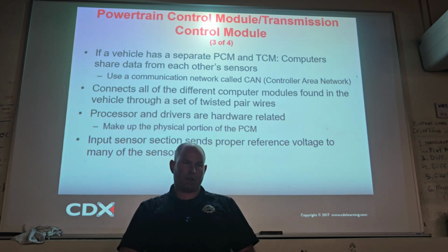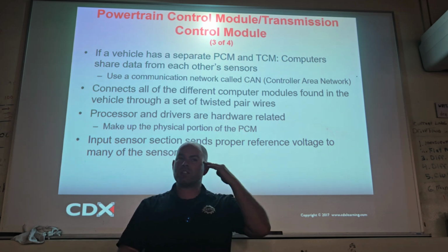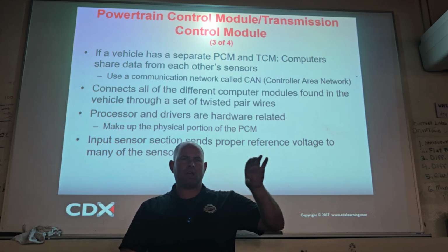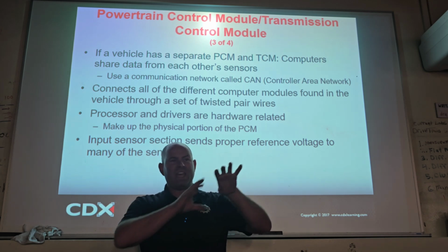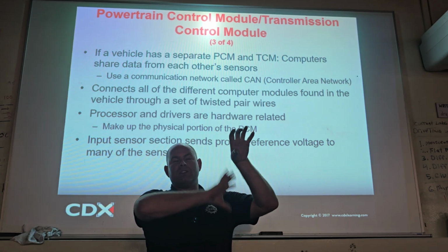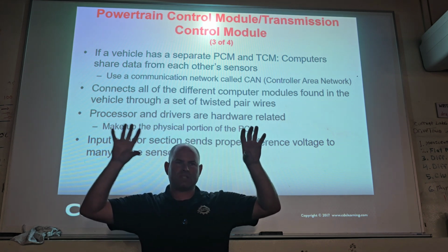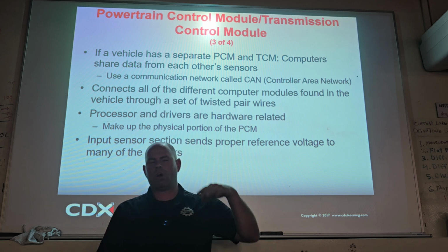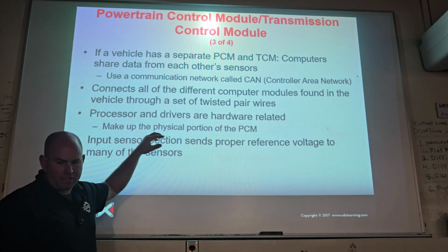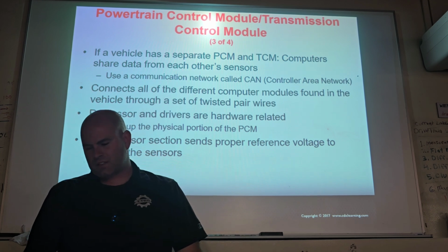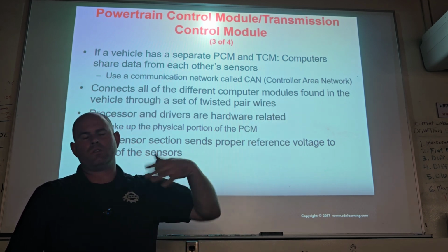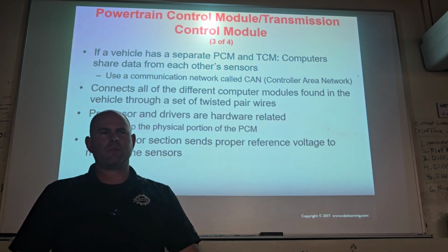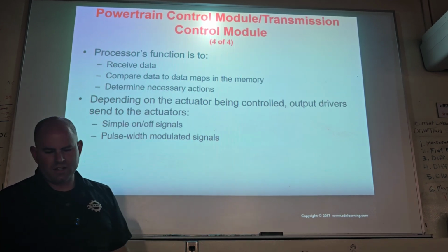Remember that story I told you on the third transmission? That's what I'm thinking just in my mind, probably what's up. That vehicle may have a bad ABS module. Sound familiar, huh, Renee? If the ABS module is no good, it's not getting vehicle speed and it's not multiplexing it out to the TCM. The TCM may not upshift because it can't tell what speed it's going. Make sense? So you also have to understand a little bit about the network too. But it's not really that complex. If you can't communicate with the ABS module, you got to troubleshoot the ABS module. Do not put a TCM in it. Do not put a transmission in it. Fix the ABS problem. They're related.